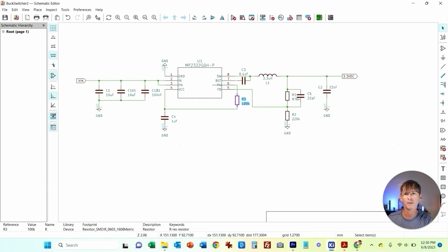And typically, it's supposed to be 3.3 volts and it's slowly ramping up there. You don't want to feed that ramped up voltage to all of your circuits because they may misbehave if they see the 1.5 volts, the intermediate voltages, as it is going up.